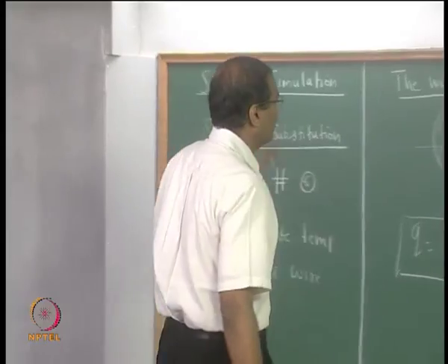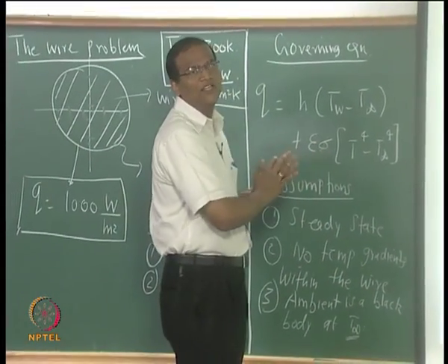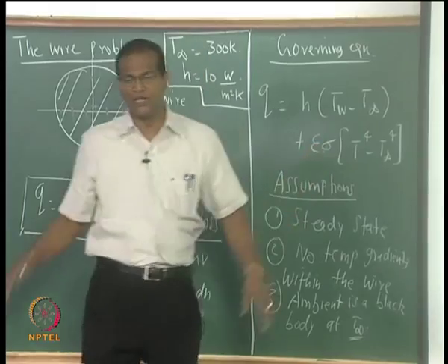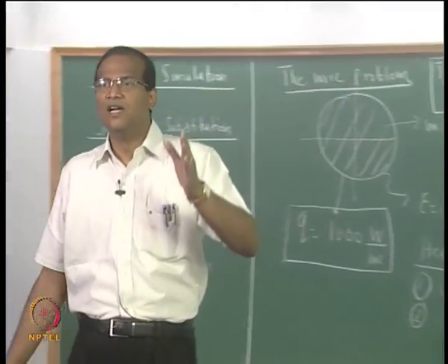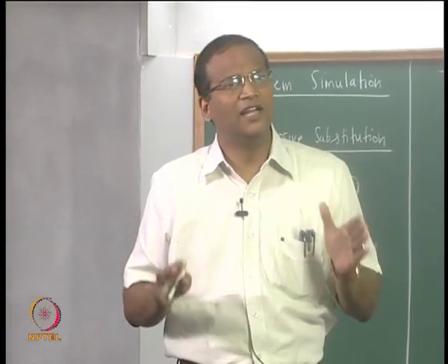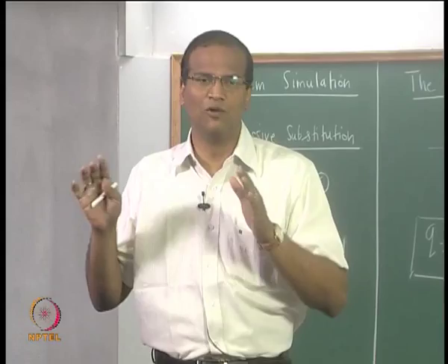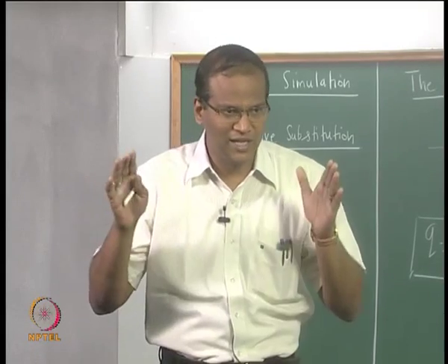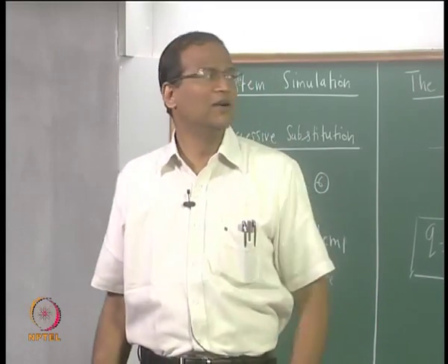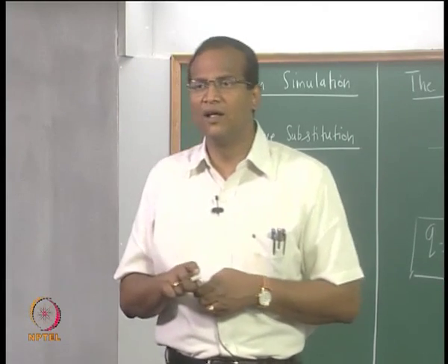Alright. Now go ahead and, knowing full well what the assumptions are, start doing the iteration. Serial number i, instead of Tw you can just take it as T: Ti, Ti plus 1, and Ti plus 1 minus Ti whole square. That is the error criterion. Decide on an appropriate stopping criterion.